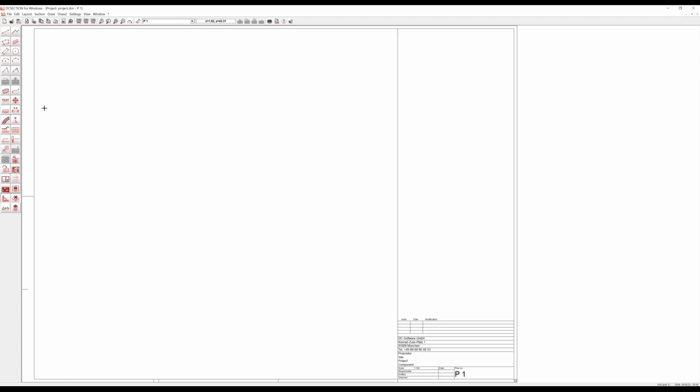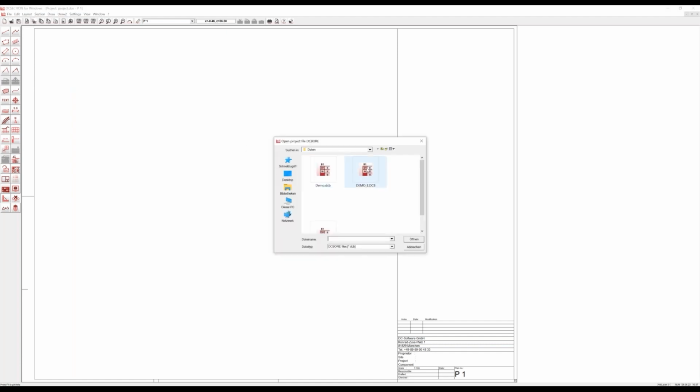And then you may add the different types of tests. The selection of the type is here under this icon, test type. And we first can select bore profiles. Here you have as well dynamic probings, cone penetration tests, sieve analysis, and so on. So we want to use bore profiles, select a project file of DC bore.